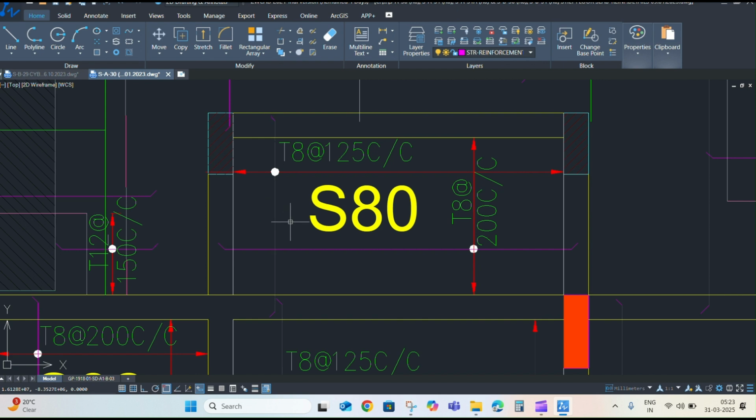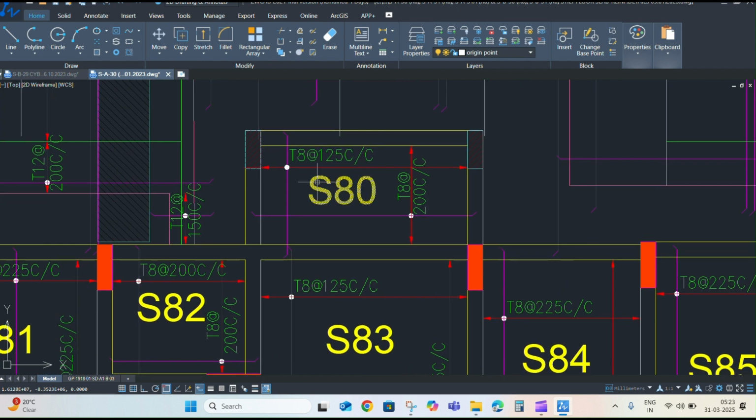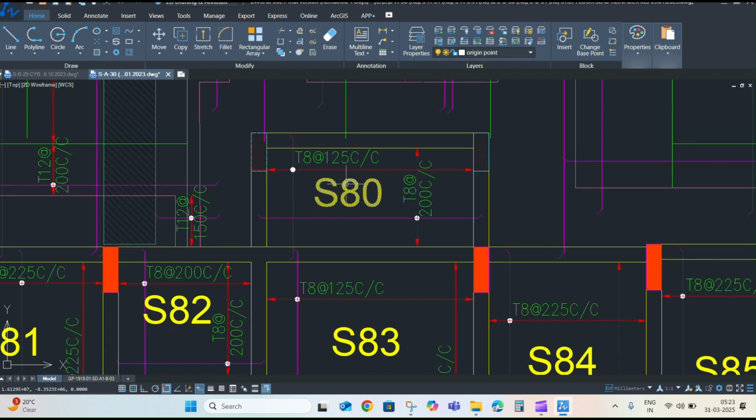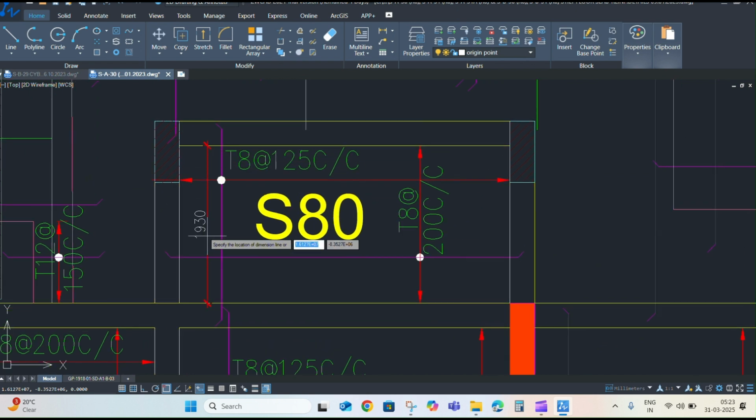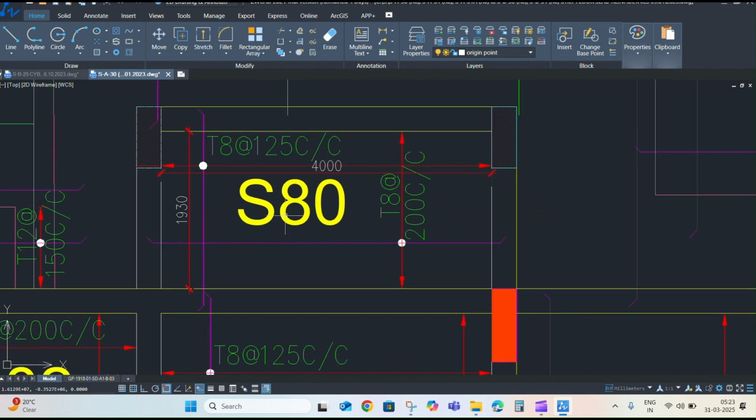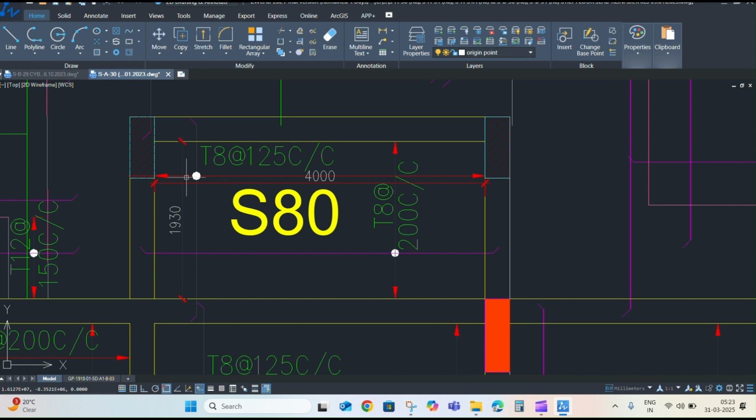Dimensioning. Properly dimensioning your structural components is crucial. Use AutoCAD's DIM tools to add measurements to the drawing accurately. Drawing tools. Master tools like line, polyline, hatch, circle, arc, and rectangle for creating the different parts of your structural design. Annotations and text. Structural drawings usually have a lot of annotations for materials, quantities, or specific instructions. Use AutoCAD's MTEXT and DTEXT to add notes, along with leaders to point to specific details.